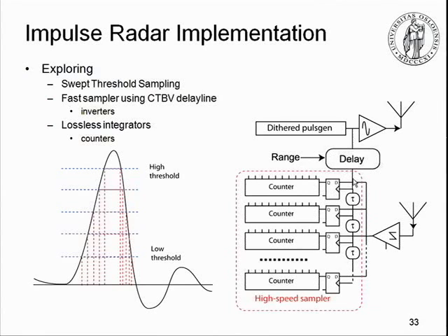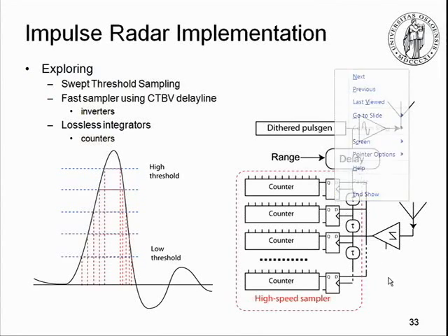And you see what we do here, we only delay the clock input. The sampling time is set by, again, our familiar delay line. But this is a very high-speed delay line that gives us actually close to 70 gigahertz in the latest implementation, sampling or depth sampling.